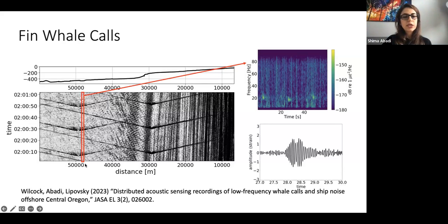So, a very tiny section of the cables over time. What you are seeing is the fin whale vocalization around 20 hertz. This is the typical fin whale call. It's a downsweep, a very short period, about 1 millisecond, and the center frequency is around 20 hertz. We see 3 of them here, and if you look at another spectrogram here, you see another 3.